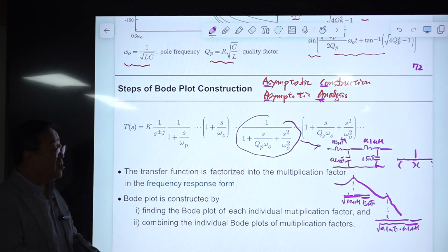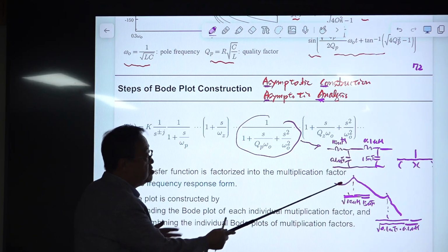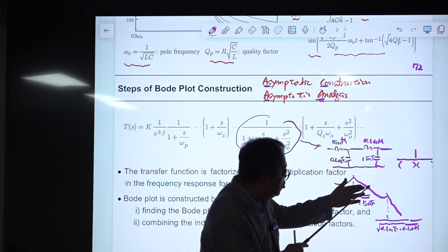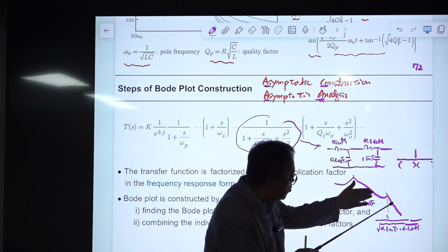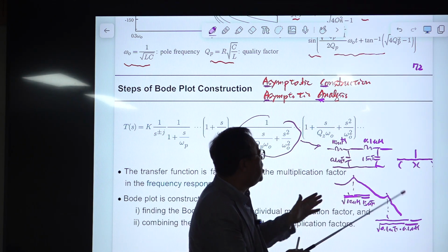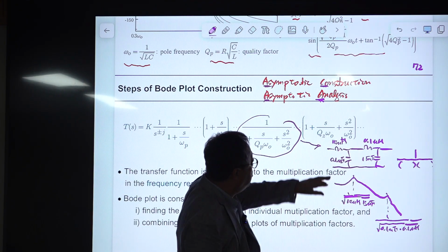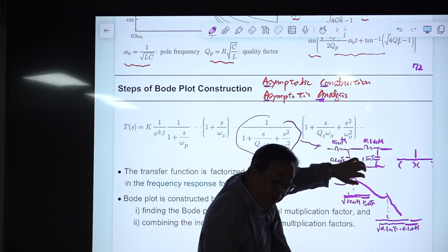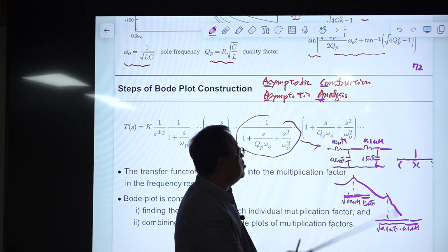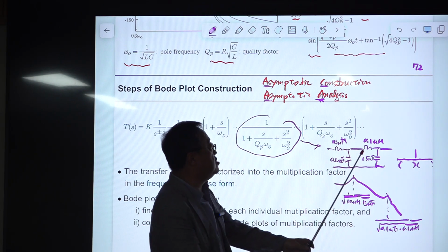When you are designing, suppose you want some attenuation. This is very good. This is a huge attenuation. This is -40 dB attenuation. Another -40. So the total is -80 dB attenuation. It's much better than combining this together into a single FET inductor and FET capacitor. You use about the same money, but the performance of that filter is very, very bad compared with this one. Okay? So always this is the good approach.